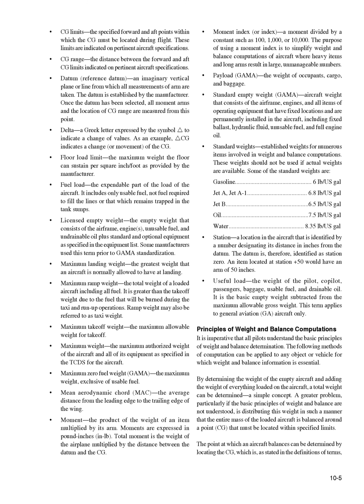Principles of weight and balance computations. It is imperative that all pilots understand the basic principles of weight and balance determination. The following methods of computation can be applied to any object or vehicle for which weight and balance information is essential. By determining the weight of the empty aircraft and adding the weight of everything loaded on the aircraft, a total weight can be determined, a simple concept.